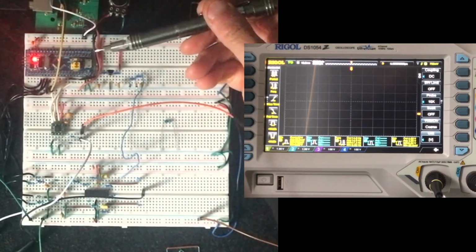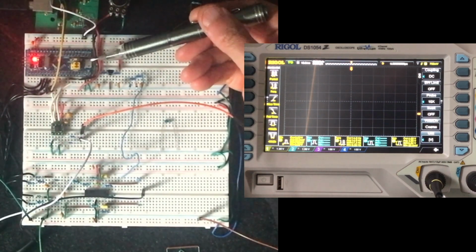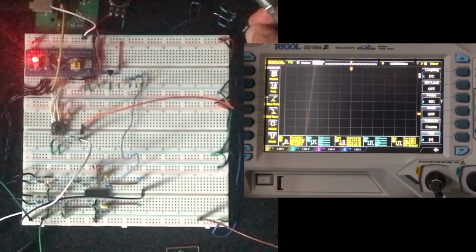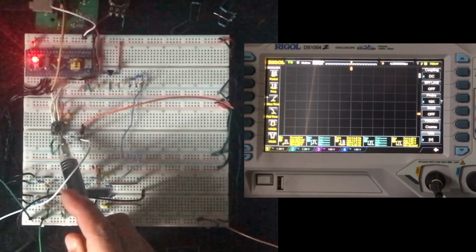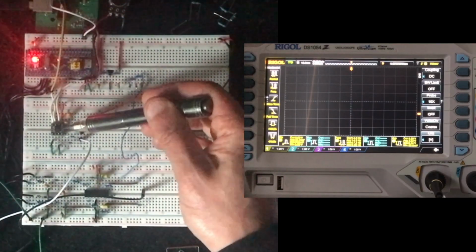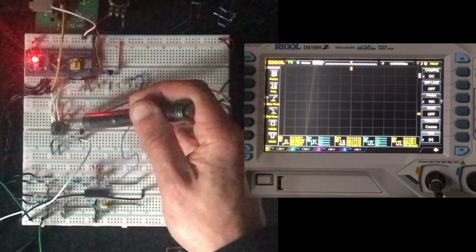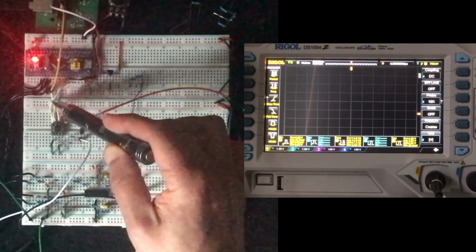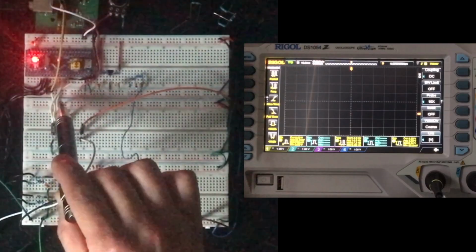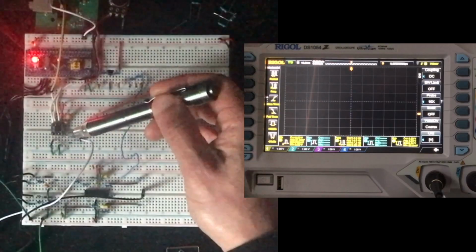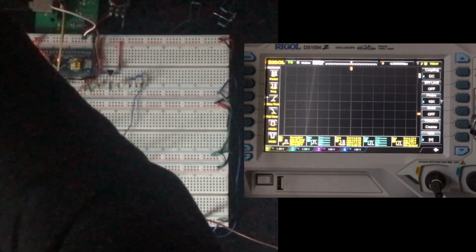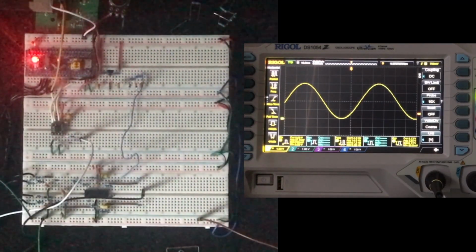So I'm using the Blue Pill microcontroller. This is a 5-volt regulator. I am using it to power the MCP4822, which is this chip right here. Here are my bypass capacitors, one tantalum, one ceramic. The 3 SPI channels, the 3 pins are connected. There are these 3 right here. And then output 1 is going to the yellow output, channel 1, which is creating that sine wave.